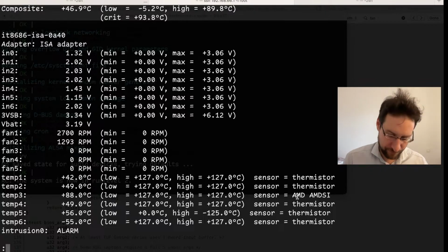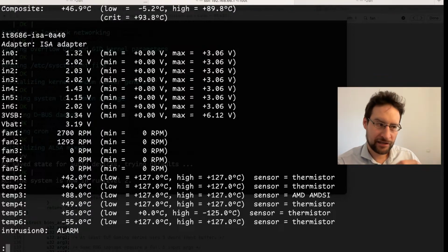Obviously now I am pretty much loaded here. A more accurate reading would be comparing idle times: let it idle and saturate temperatures to ambient plus idle, like PCH, VRMs, CPU. After 10, 15, 20 minutes of idle thermal saturation, reboot, and then you can match that to whatever the BIOS shows more reliably than under full load. My pro-tip there. It's not ideal, but it's better than nothing. At least you have some voltages that may or may not be right, mostly maybe, although the 3-volt battery probably looks relatively reasonable. I mean, you can take the battery out now, right?